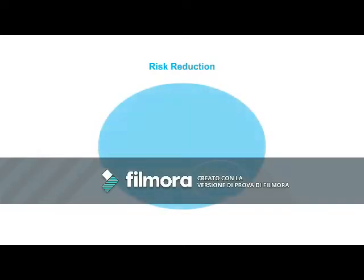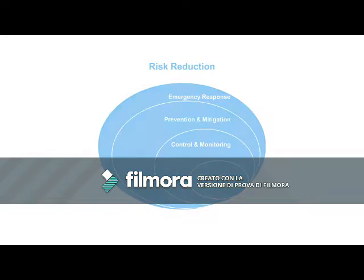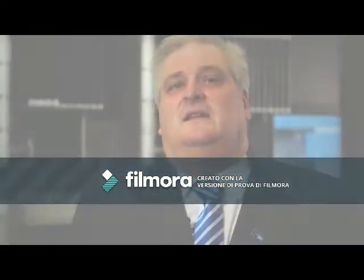We need separate layers for control and monitoring, prevention and mitigation, and emergency response. Each of these three layers addresses a specific part of the risk reduction required. Together, the layers address the risk created by the entire production process. To meet the standards, the function covered by one layer of the protection must be sufficiently independent from the functions covered by the other layers.